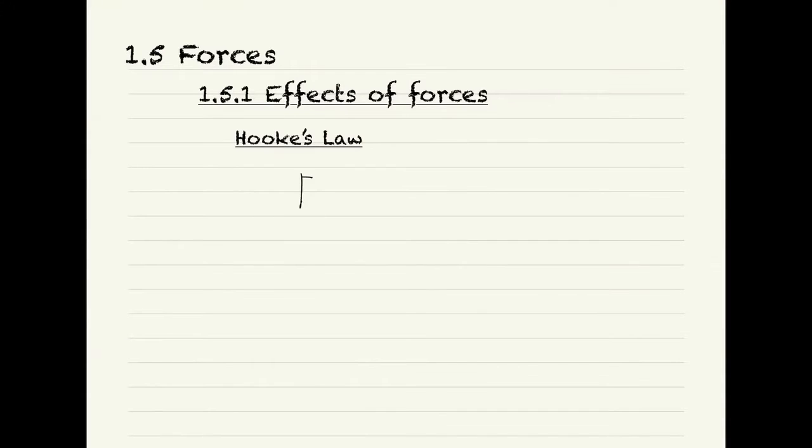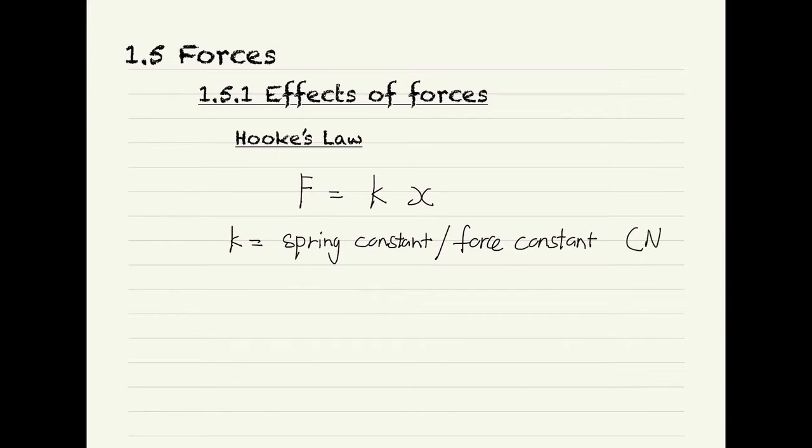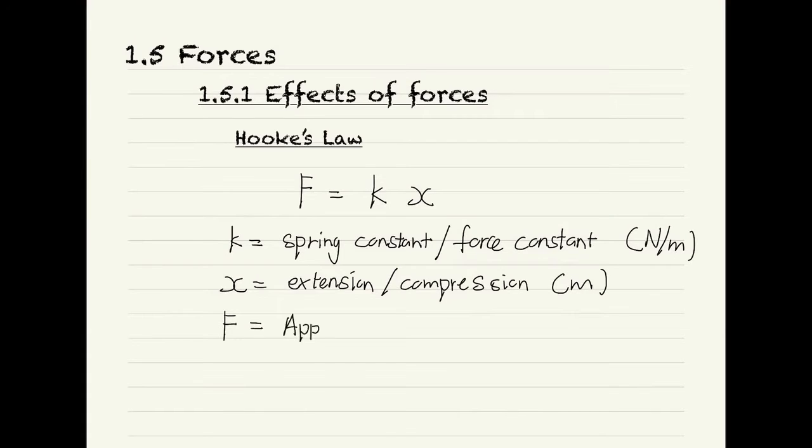From Hooke's law, we have one formula F equal to Kx. K is spring constant, or sometimes also called force constant, with unit Newton per meter. X here is extension or compression with unit meter. Then the capital F here is applied force or load with unit Newton.